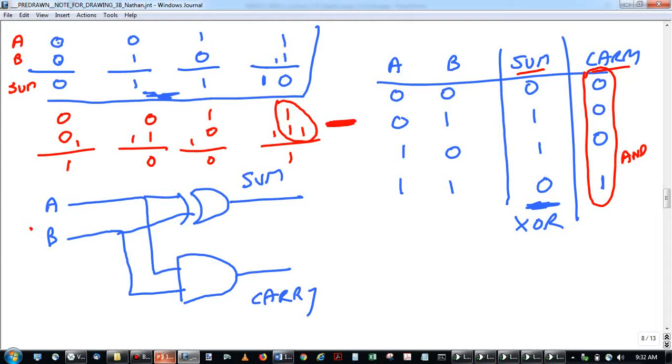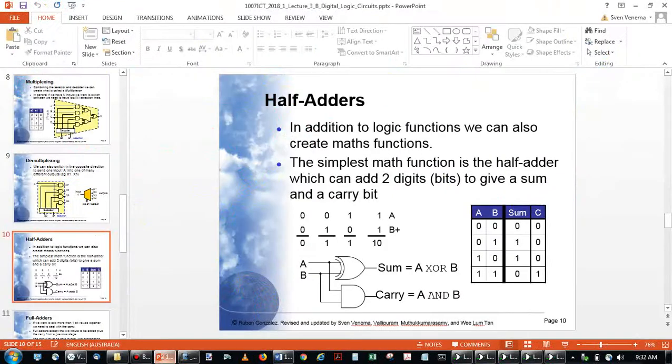If I read this, I'll say, look, it's 1 plus 1. That's this one, right? That's this guy. And then what do I do next? I add one more, right? So if I could have a C input coming in here, a carry in, for example, if I could plug that in somehow, that would fix my half adder problem. We can't just fix it like that. What we actually have to do is we have to use something called a full adder.